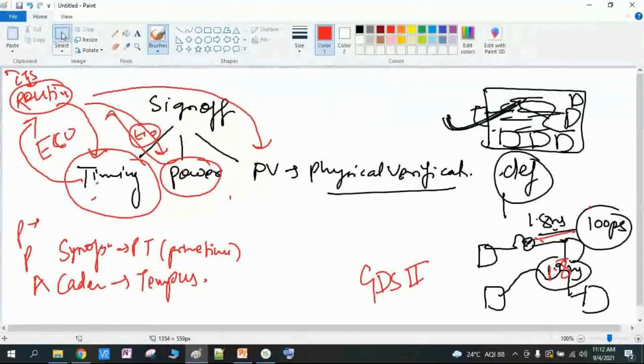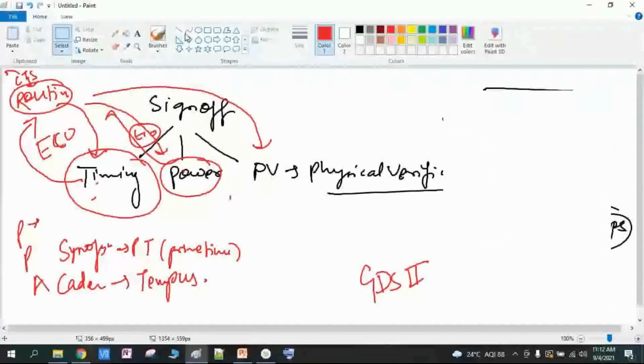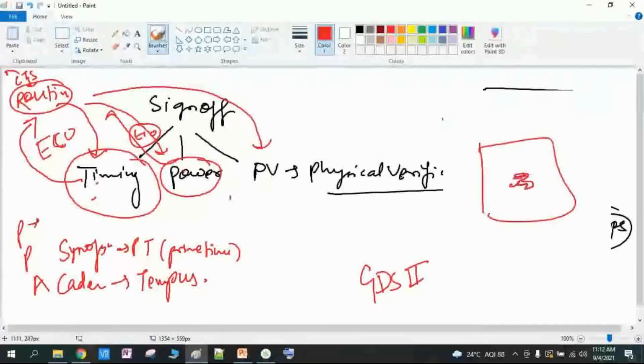They will tell that, see, in this region you have more power dissipation. Can you please see, in this area you have a lot of power dissipation, can you fix this? Can you add some extra cells that is called a decap cell? That decap cell will provide power. Can you add those cells here? I will say, okay, fine, I will again open the routed database, take their feedback and fix it. You got the point? The decap cell and all, we will discuss later on. They are telling that this is the medicine, can you give it to your routed database? I will give the medicine.